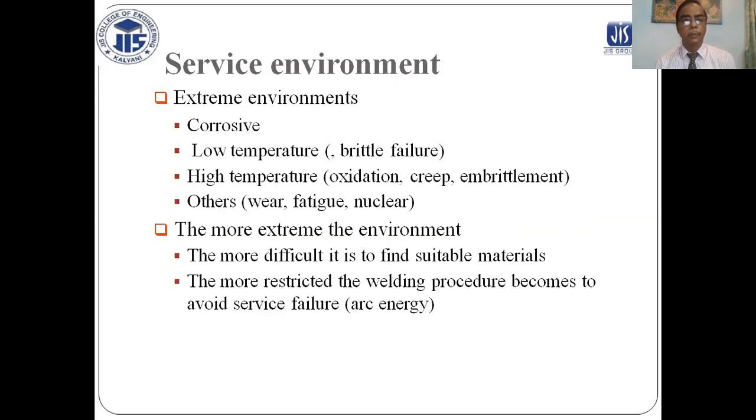Service environment: extreme environments such as corrosive, low temperature, which causes brittle failure, and high temperature, which causes oxidation, heat, and embrittlement. Others are fatigue and nuclear. The more extreme the environment, the more difficult it is to find suitable materials, and the more restrictive the welding procedures become to avoid service failure.